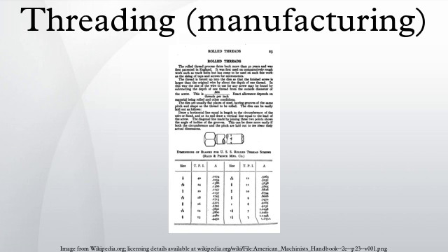Overview of methods. There are various methods for generating screw threads. The method chosen for any one application is chosen based on constraints: time, money, degree of precision needed, what equipment is already available, what equipment purchases could be justified based on resulting unit price of the threaded part, etc. In general, certain thread-generating processes tend to fall along certain portions of the spectrum from toolroom-made parts to mass-produced parts, although there can be considerable overlap.